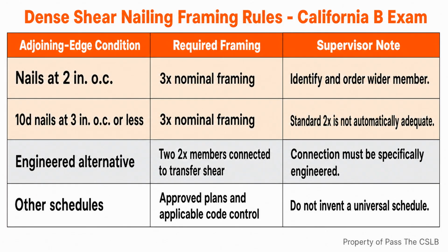Now I want to walk through the 2 defects that can fool a quick visual inspection. The first is a shiner. A shiner is a nail that passes through the panel but misses the framing. From the exterior, the head may sit in a neat row. From the interior, the exposed shaft reveals that the fastener anchored into nothing behind the panel. A shiner contributes no intended shear connection at that location.